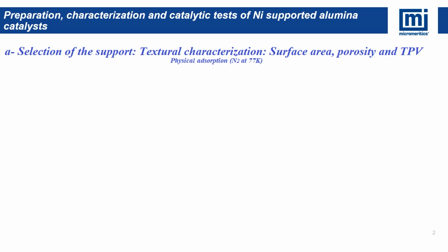So we always speak about effective pore size. The effective pore size is going to control the diffusion of the molecules. The pore size should be about 4 or 5 times larger than the diameter of the reactant molecule, so it can diffuse very easily inside the pore to find the active species dispersed inside the internal pore. The pores also have to have a certain size to let the product diffuse out from the pore to the external way.